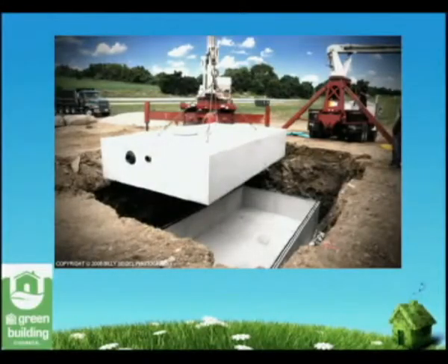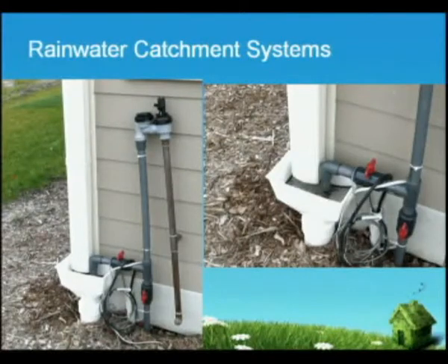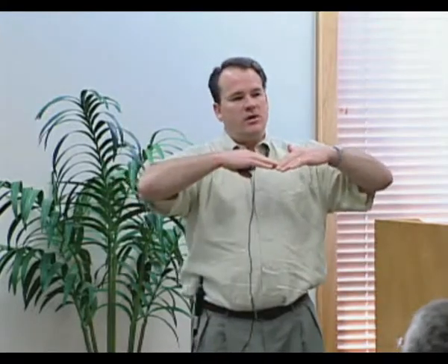This is a pretty big system that we put at the Trend Home. We actually used about a 5,000 gallon system, basically a container, to capture the rainwater coming off the roof. What we did here then is we tied in pipes to that system through this right here. We have a little filter up here that captures any leaves, things like that that might come down. But really the maintenance of this system is relatively minor compared to some other systems, and primarily it's because of the type of roof material that we used on the house.